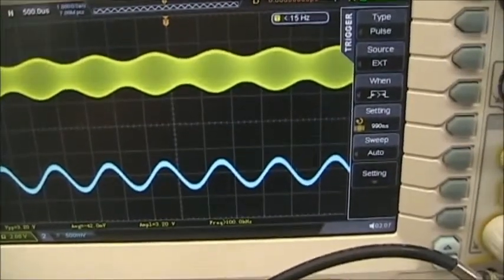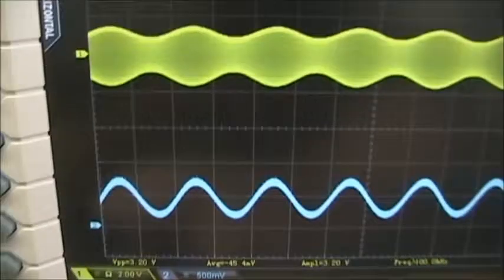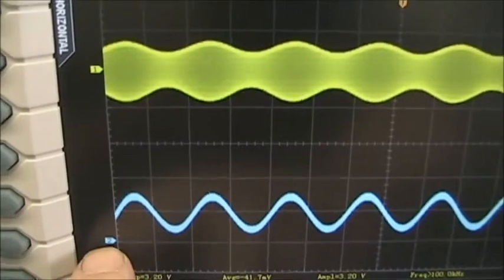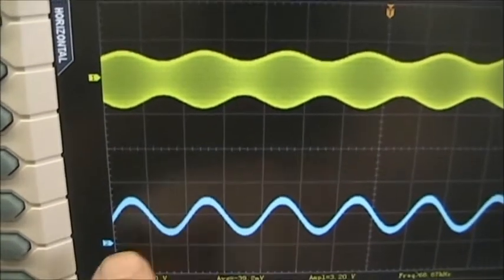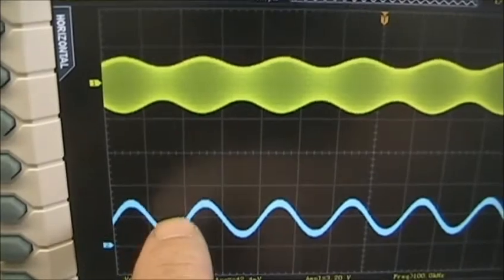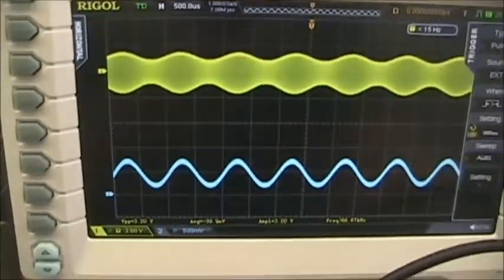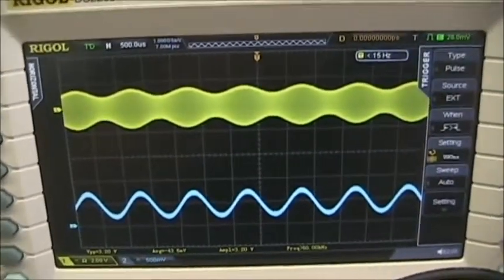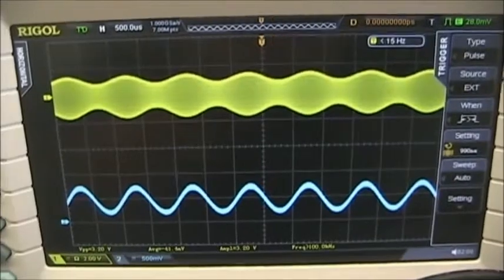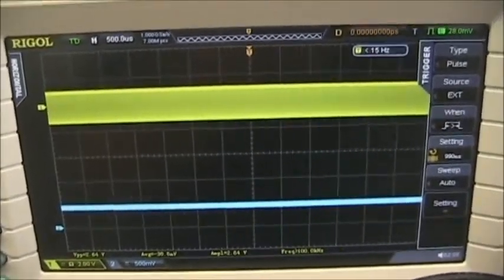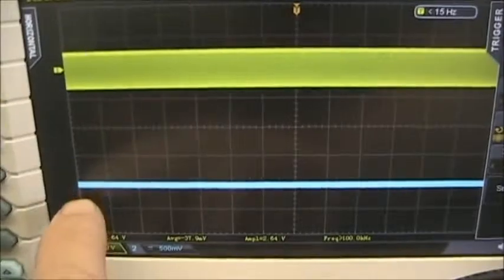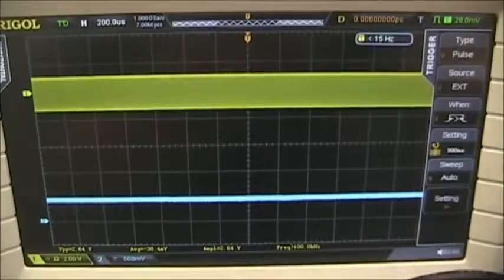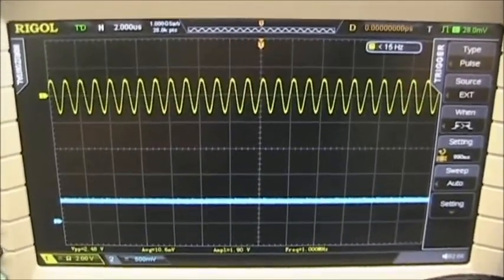Back to a sine wave, if we look at that. Now, one thing you will notice, the signal is shifted by a certain DC level, because the diode cannot reverse bias and carry the AC signal, so there's always a bias associated with that signal. Now that bias is actually associated with the carrier. If I go back and set the AM depth to be 0, we will see that I have a DC signal on my demodulated content, because this AC modulated signal is just being rectified.